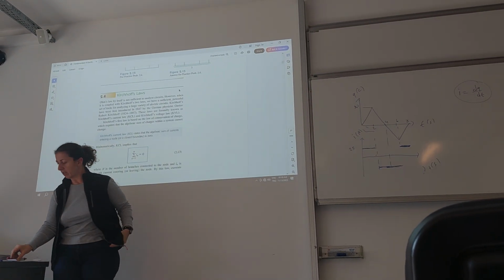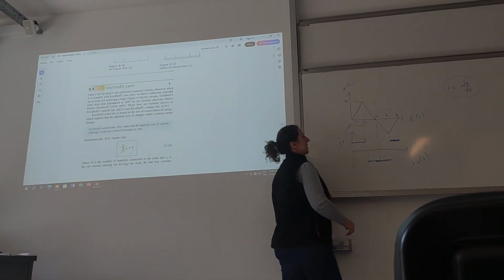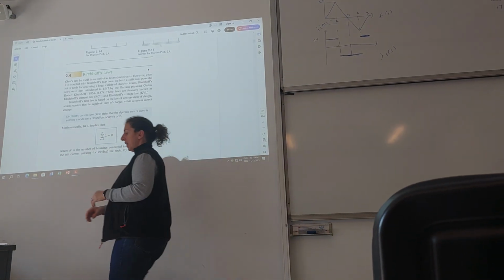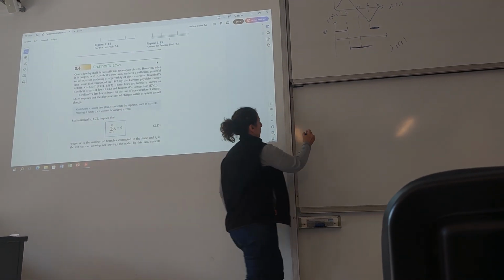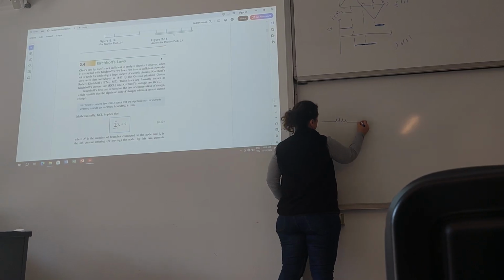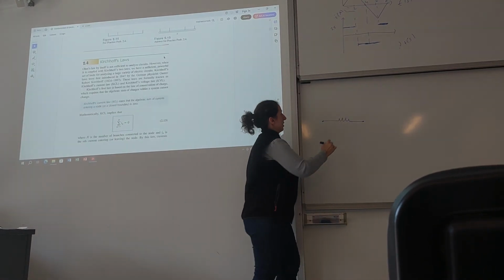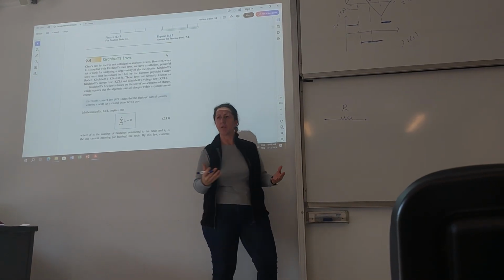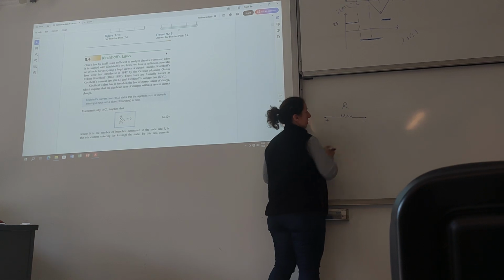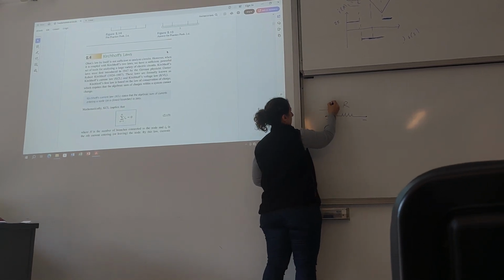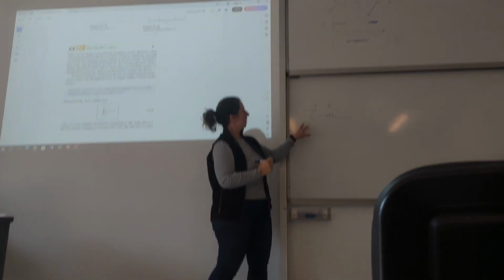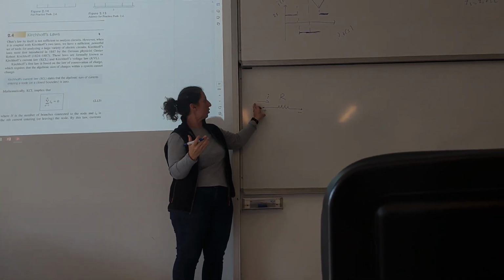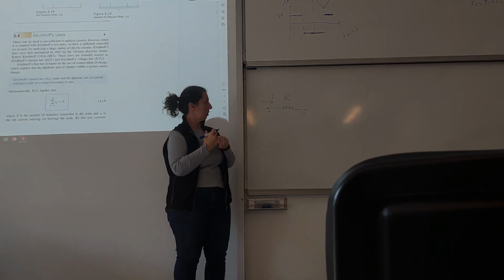And remember, there's a simple rule. Again, this is not how we teach it in Physics 102, but from the perspective of electrical engineers. Since resistances are passive elements, we would like to always get positive power for them. So most of the time, what we accept is that distribution: current goes from the positive side to the negative side, because that's actually what is expected. Current should flow from the high side to the low side.